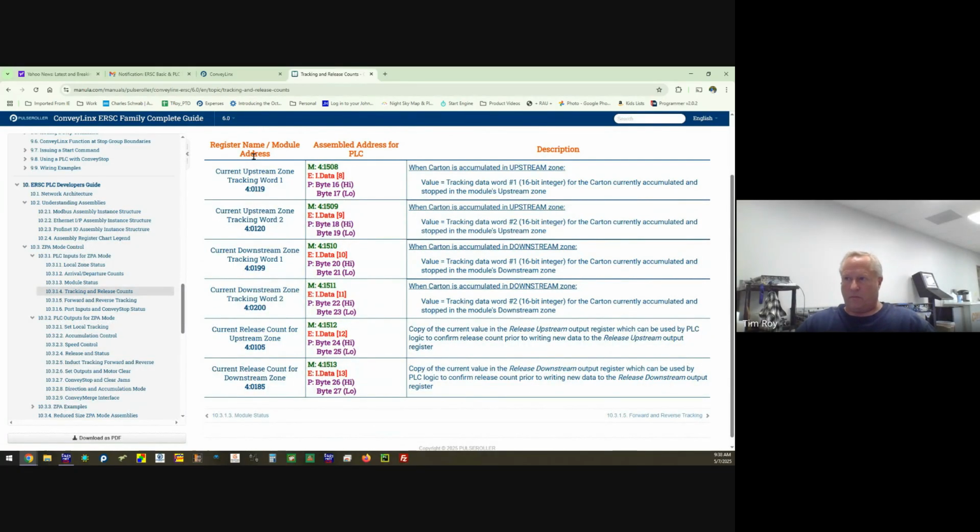Tracking. Currently, for upstream tracking we have 2 registers, and for downstream it also has 2 registers. You can combine these as one DINT or use them as separate registers. If you use the add-on instruction, I followed the previous format, I guess, as my boss, and in the add-on instruction, we provide tracking as a DINT.